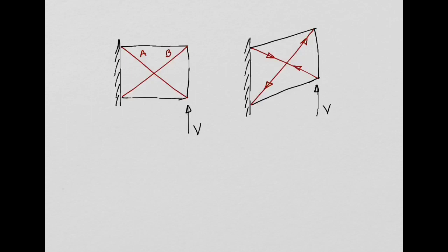And what is going to happen is, if we are working with a thin web in our spar, and if we assume that this strut A has a very high slenderness ratio, it means that under this compressive force in strut A, it is going to buckle, okay? So what is going to happen after it buckles is this, so I can draw a third one here below.